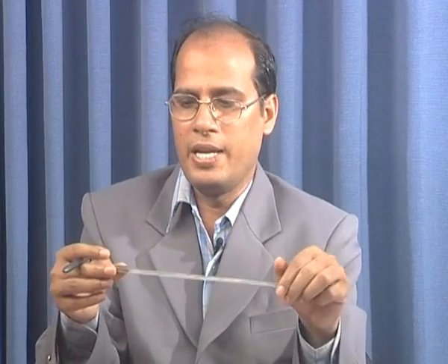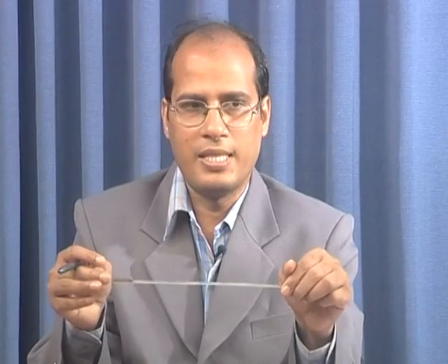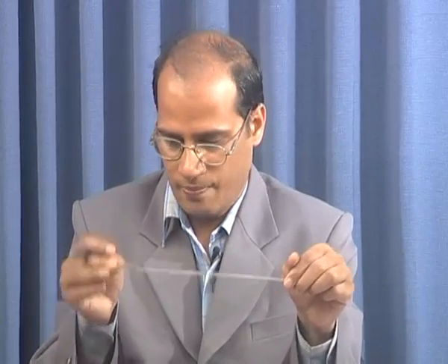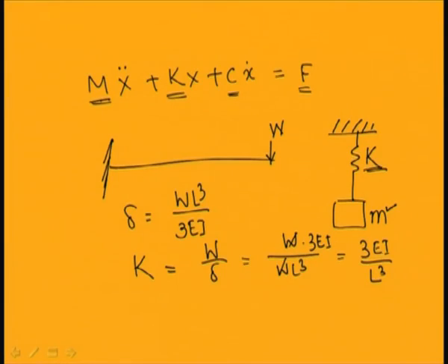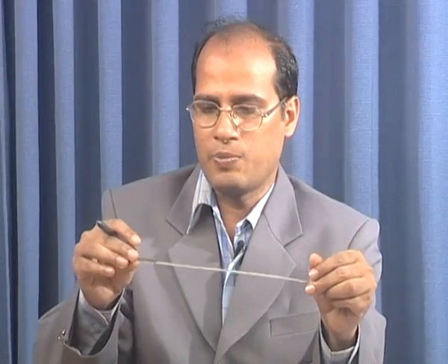If there are infinite masses and springs in this continuous system, then you have an infinite number of natural frequencies associated with it. So you should not model it as a single spring and mass system to find the natural frequency or the response of the system.